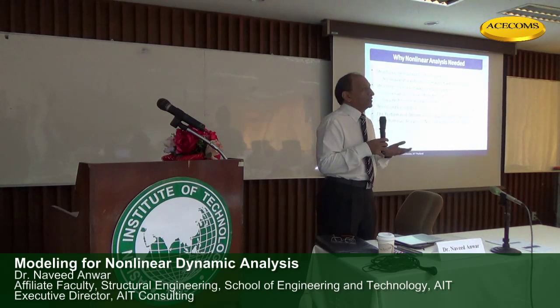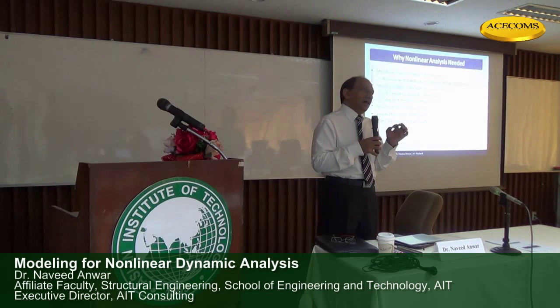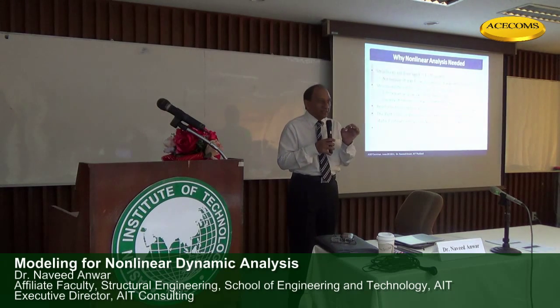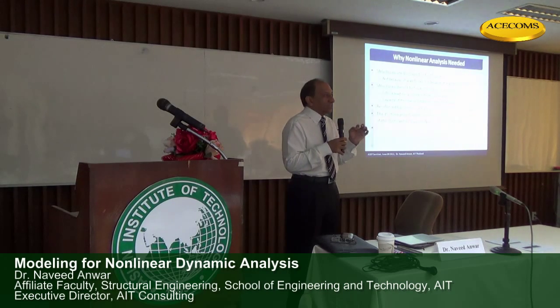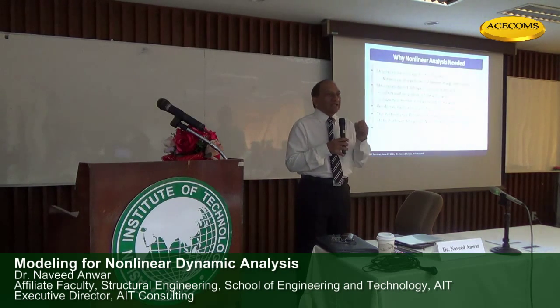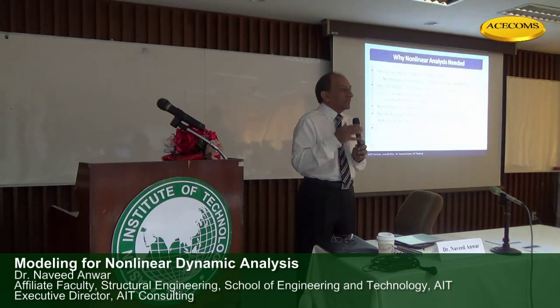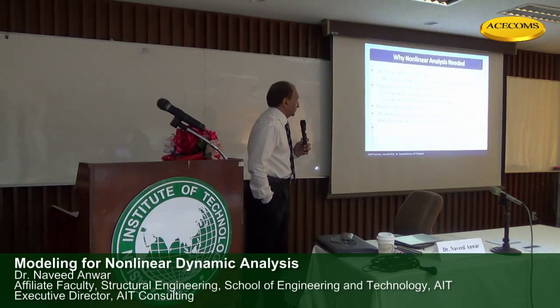So how do we know these results are not correct anymore? Because at some point, those results start to be incorrect because that deflection was not possible. So the deflections obtained by the elastic analysis and the corresponding forces cannot be reliable after a certain level. That means we need the nonlinearity to be considered.